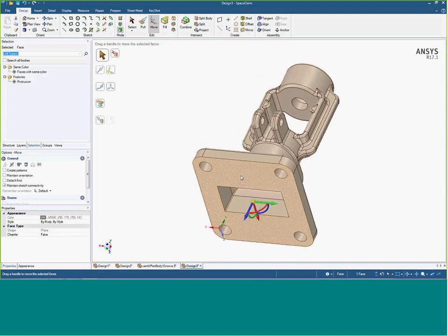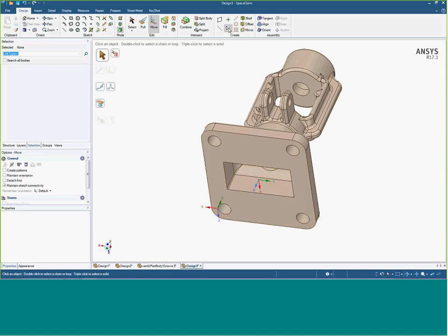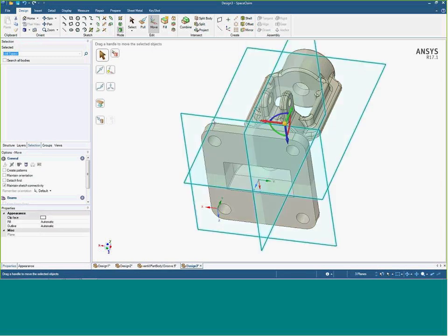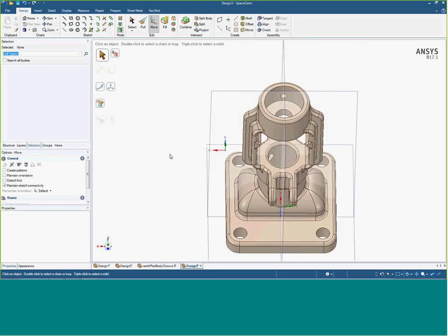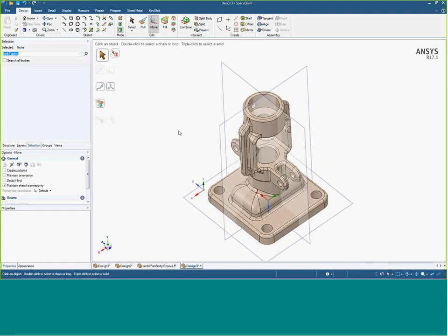If I just select the bottom surface down here, it puts a little origin down there. That's actually the move center. I can click this option to create an origin. If I click on the origin and then click the plane button, it'll create the 3 orthogonal planes off of that. So we can use that to slice this into a quarter symmetry model.